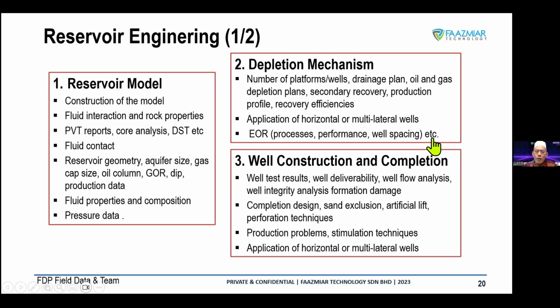Okay. When you have all this modeling, it might be completed by drilling a well. So when you do the well construction, it should be able to manage all the reservoir modeling requirements and the depletion requirements. For example, you want to run 3.5-inch tubing for your production stream, but because of the depletion, maybe we need to think about having 4.5-inch tubing. All this discussion is related from one discipline to another.